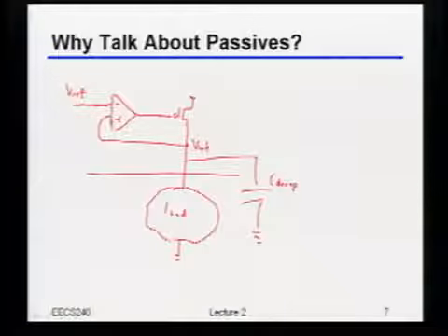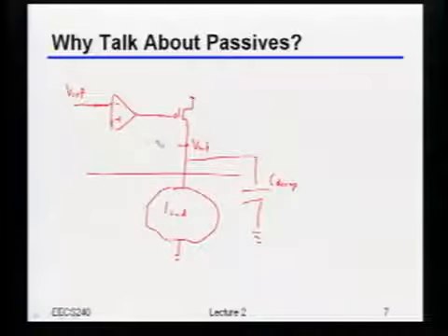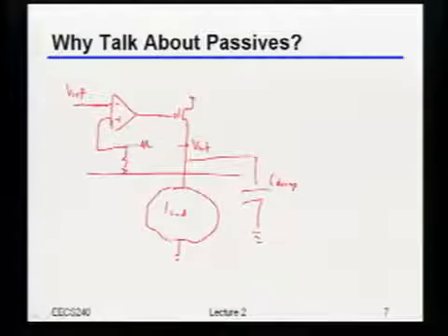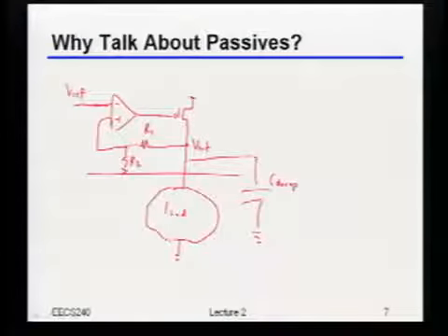You want resistors on the feedback loop. Why do you want resistors in the feedback loop? To control the ratio of the VDD to whatever output you're trying to get. Okay, you could indeed do that. I think what you're saying is this: I'll have an R1 and an R2 over here. This is a great example.